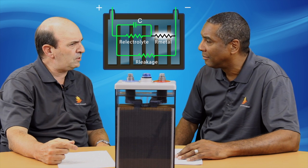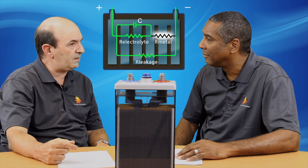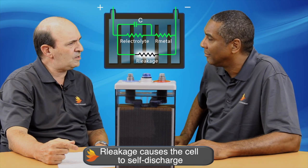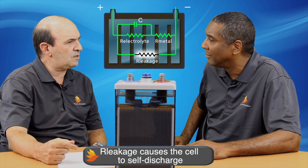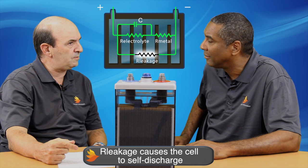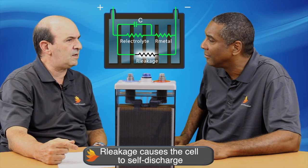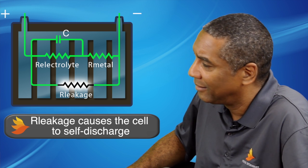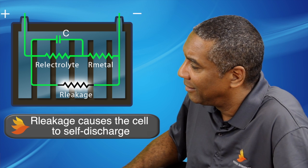Our metal is a fixed resistance associated with the metallic interconnections between cells in a battery. It doesn't vary or change with temperature, but it also limits the maximum current a cell can produce. In broad terms, our electrolyte and our metal are about equal in magnitude, and the combination of the two is what is commonly called the internal resistance of a cell. Our leakage is a very high resistance that causes a battery to self-discharge when not being charged. It's not measurable resistance, but including it in the model does help us to understand why batteries left uncharged for long periods of time will eventually lose all their charge.